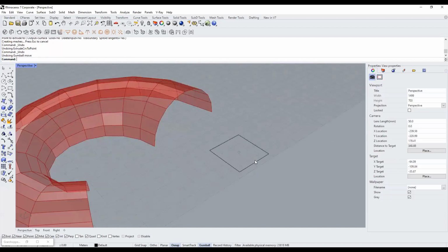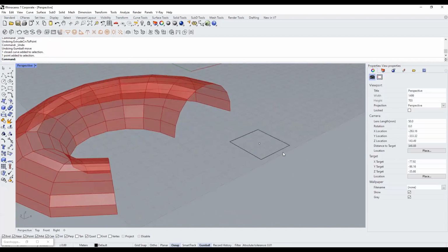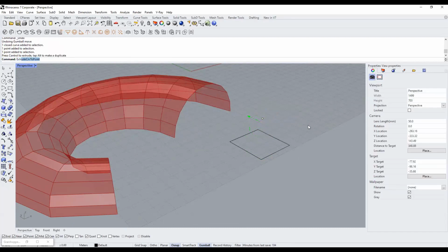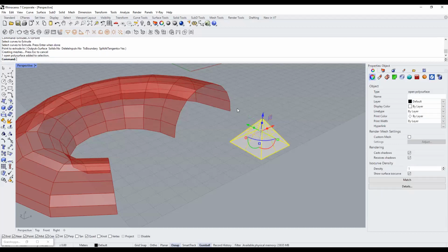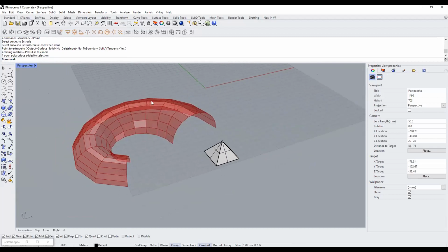I repeat again, we have the panel, find the center of it. After finding the center, we move the center point, and then we create the surface using that. That's it. So 3 steps: find center, move center, create the surface. Now let's try to do the same thing in Grasshopper on all of these panels.